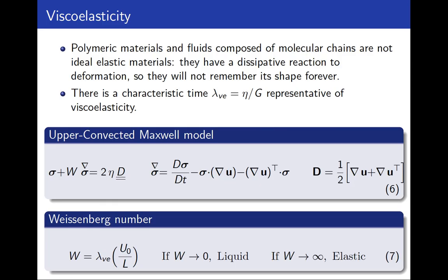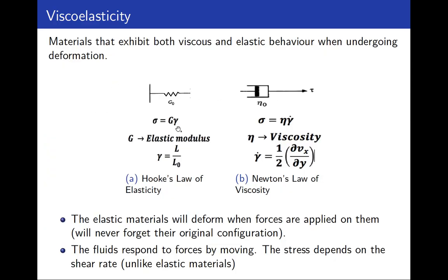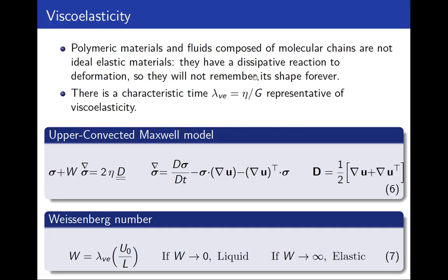When you stretch them and then remove the force, they will never return to their initial configuration because they have a dissipative reaction to deformation. So polymeric materials can usually be seen as a spring connected to a dashpot. Fluids exhibit a viscous part that will oppose deformation. So we tend to say that fluids and polymeric materials will not remember their shape forever.